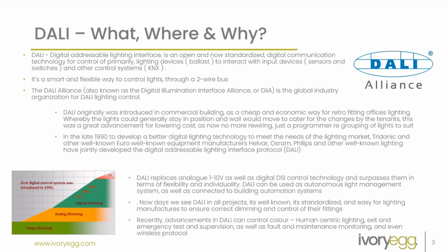So what we see a lot with lighting manufacturers is they've got a light fitting, and they're never really sure about the best means to dim or control that fitting. But they can make sure they have a corresponding Dali driver that's been matched to suit it, or they've tested to suit it, and then they can sell it in many markets that way. There have been recent advancements in Dali, and it can now control color.